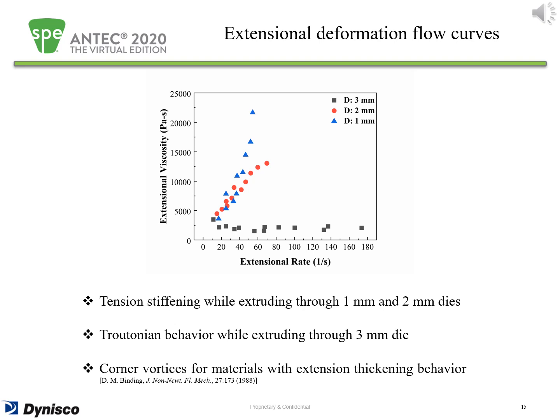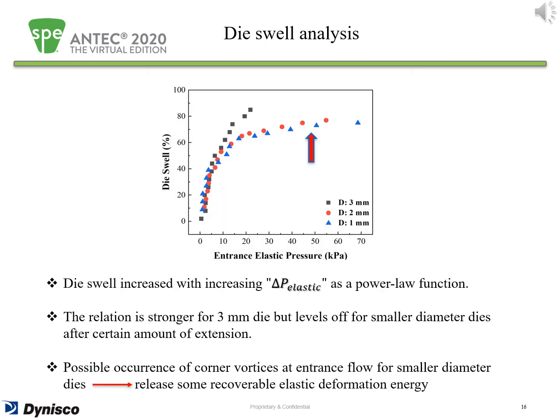In our work, extension stiffening behavior was observed for LDPE melts extruding through flat capillaries with diameters of 1 mm and 2 mm, which can intensify the occurrence of flow instability and corner vortices at the entrance of those dies. In order to predict the entrance flow pattern for various dies, the extrudate swell behavior of LDPE melts was analyzed